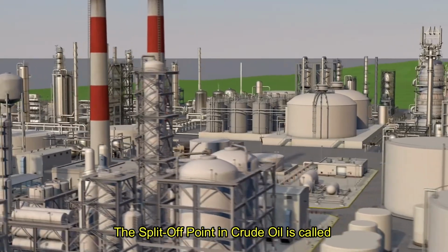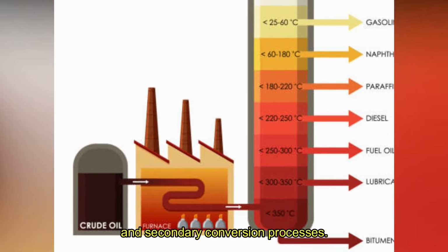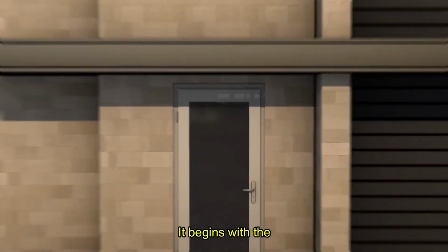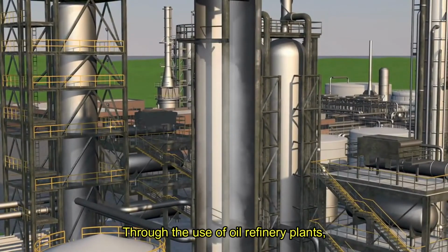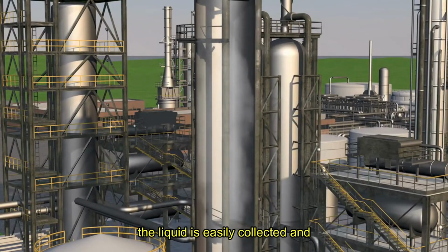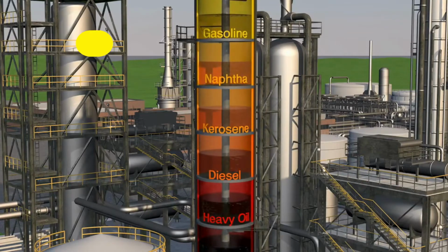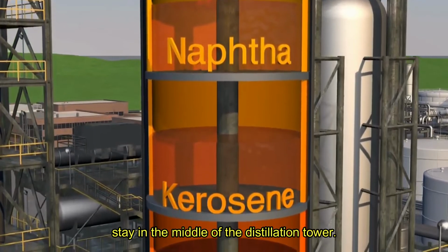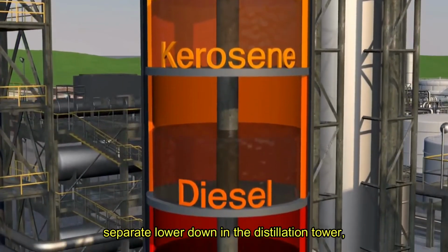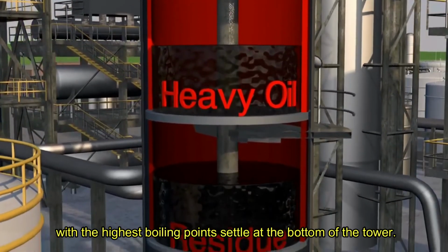The split-off point in crude oil is called refining. It essentially consists of primary separation processes and secondary conversion processes. It begins with the distillation process, wherein after the oil is superheated it becomes vapor. Through the use of oil refinery plants, the liquid is easily collected and separated by lighter, medium and heavier weight. The lightest fractions vaporize and rise to the top of the distillation tower, where they condense back to liquids. Medium weight liquids stay in the middle of the distillation tower. Heavier liquids separate lower down in the distillation tower, while the heaviest fractions with the highest boiling points settle at the bottom of the tower.